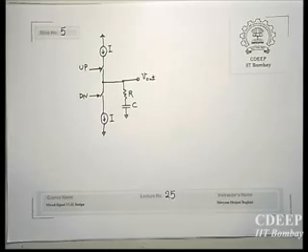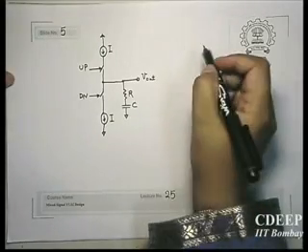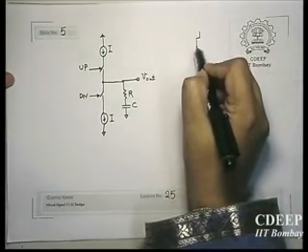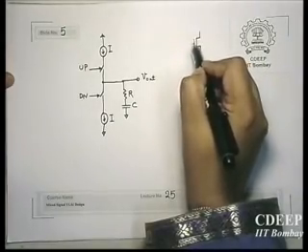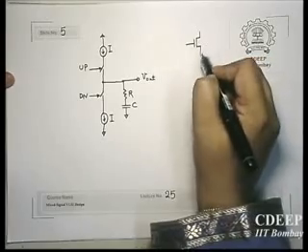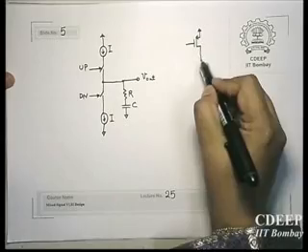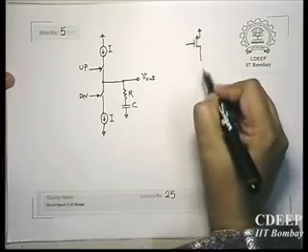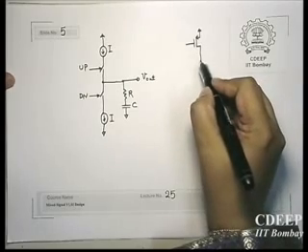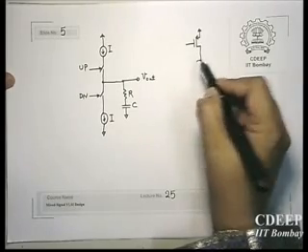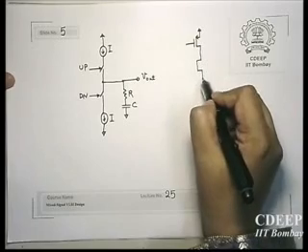So how to implement it? For example, I will tell you a very simple implementation. It can be a cascode current source or a simple one, it doesn't matter. Suppose you use a simple implementation. If it is cascode, you should add one more and then have a bias. Then you have a switch.